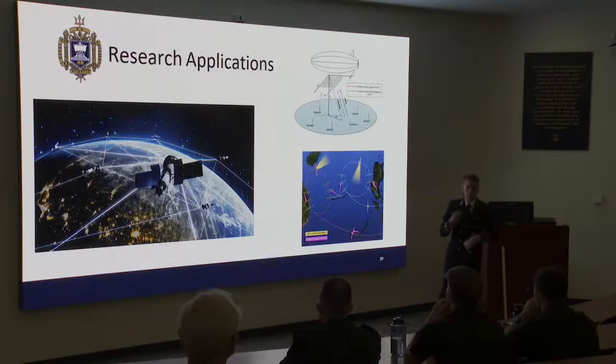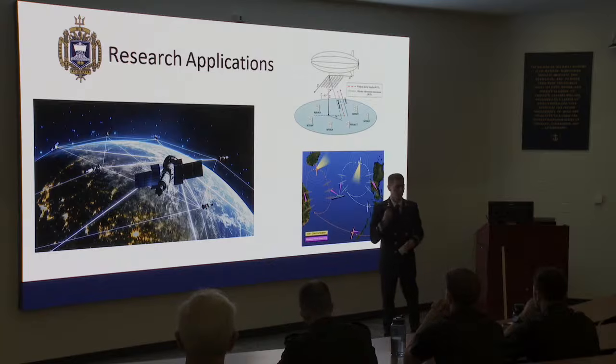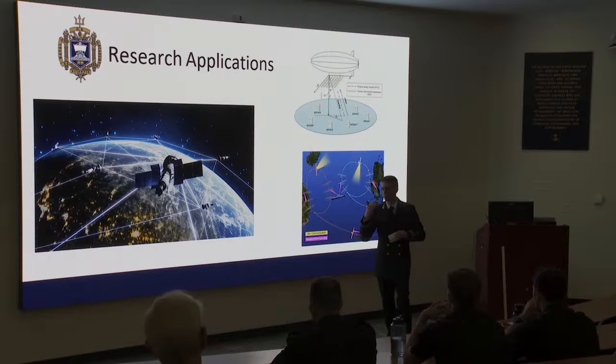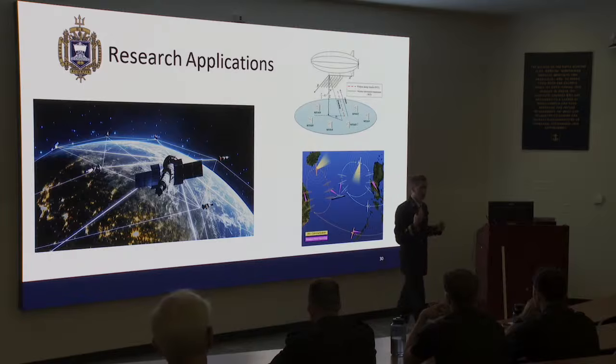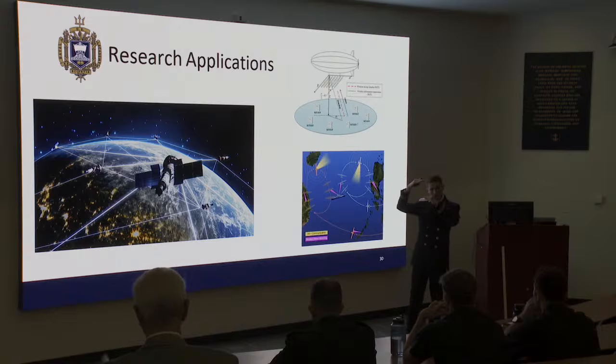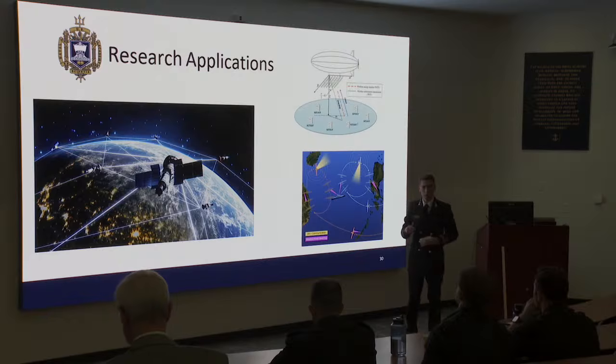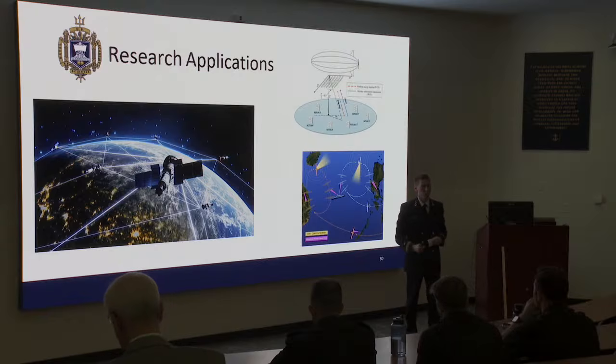So a quick reason as to why we weren't able to transmit or modulate as fast as I would have hoped, that being the noise introduced by the DAC system. We were only really able to distinguish at levels of differences of 5 millivolts within the transmission signal. Ideally, we'd be operating in the microvolt region. What that allows us to do if we can distinguish voltages at a finer level is that we can reduce the maximum amplitude modulation depth that we're operating at. A smaller maximum step size means that the settling time is faster, meaning we can modulate the system even faster.